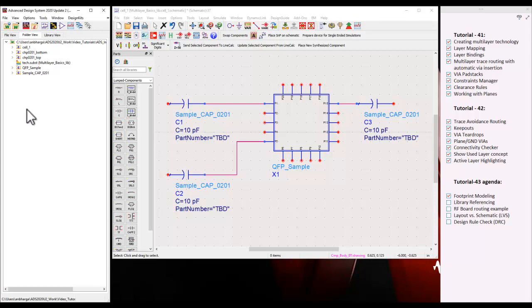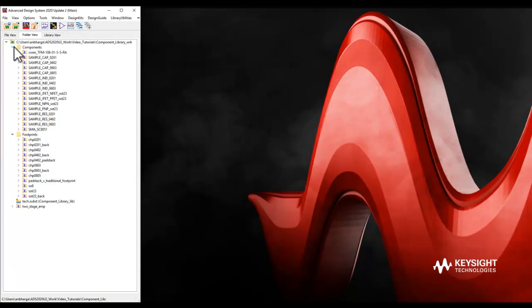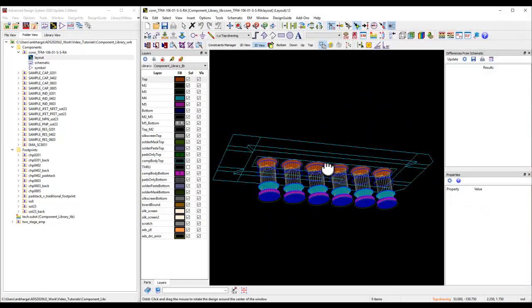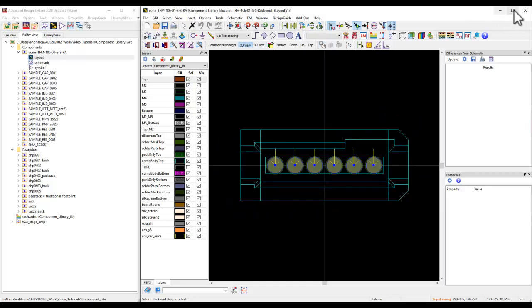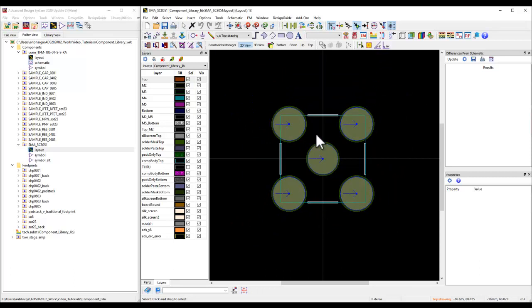So in this case, thanks to my colleague Wenlei, she prepared this example where she has created these footprints for various sizes, as you can see here. I also have various components like capacitors, a few transistors, resistors, and all that. Using the same logic, we also have a connector model here. If you look at the connector footprint and I show you in 3D, it's like a typical plug-in connector. And I also have a model for an SMA, and here is an SMA connector model, which is again a very simple footprint to create with all the information you already have.